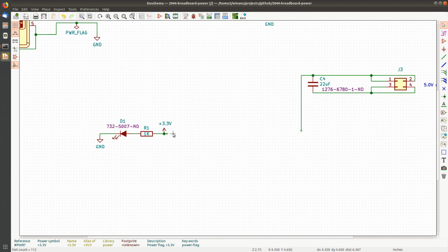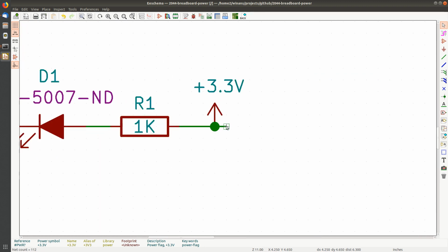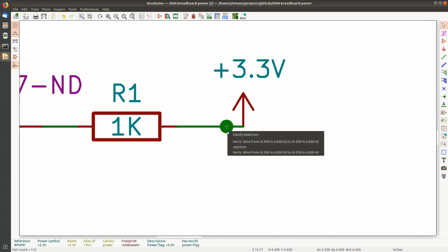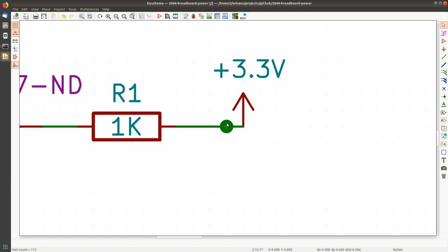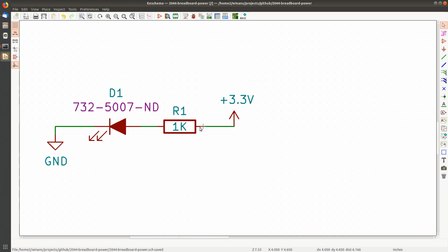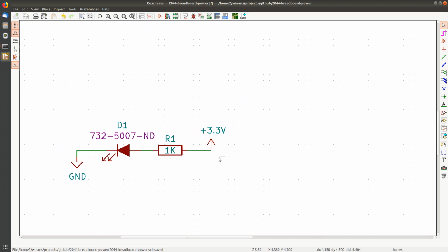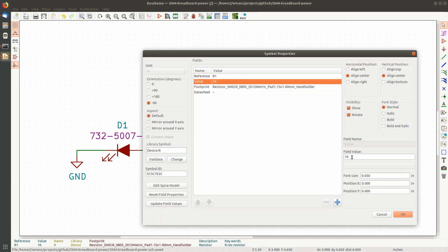And I can just hook up this LED, zoom in a little bit here. What do I say? G to grab the end of that thing. Oh, come on. Wow. Oh, for crying out loud. It's M, and move it to the end, okay. This thing, the junction, I can hit delete now. Come on, junction, okay, there we go. Save, okay. Clean that up a little bit. Now this is going to be powered off of 3.3 volts. It's no longer going to be a 1K. I'm going to put a 330 on there, the lower voltage.